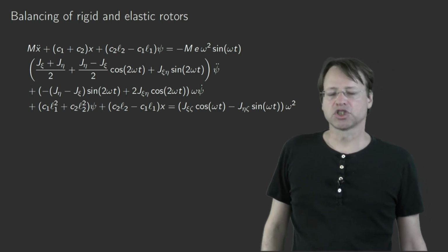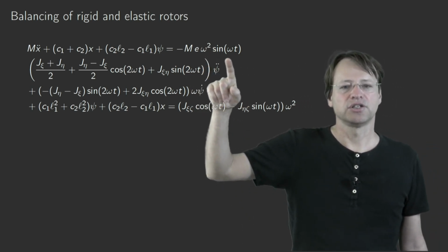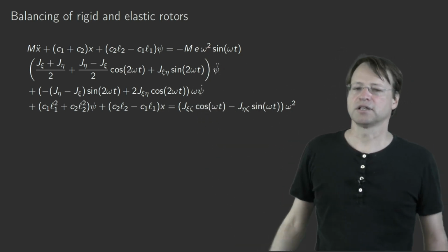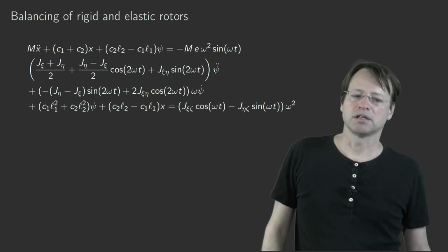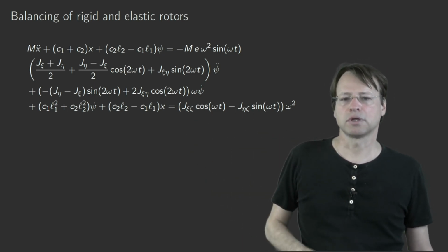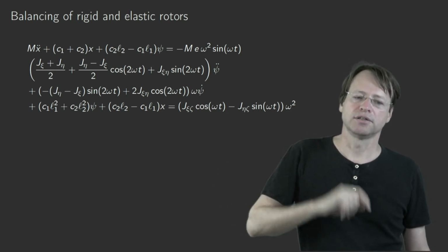second order equations. And the excitation is a classical excitation here with omega squared. So this would be from classical excitation from an imbalance, so mass force excitation. This is perhaps new, but follows, I would say, the same line. It's harmonic excitation, and it's related to omega squared.